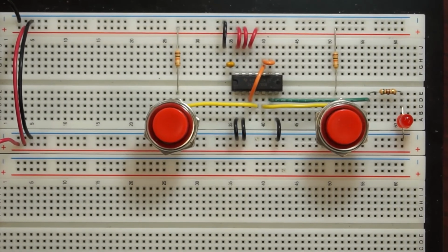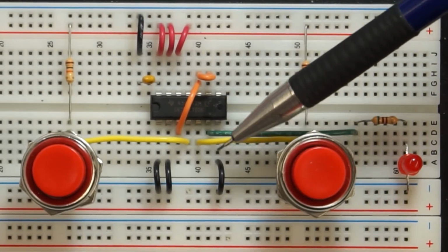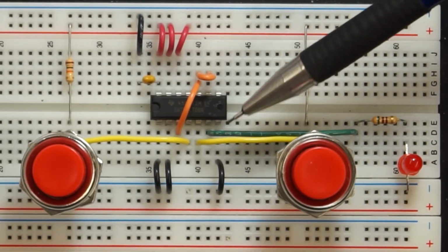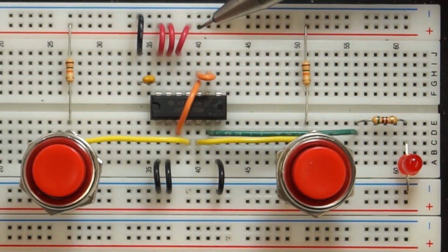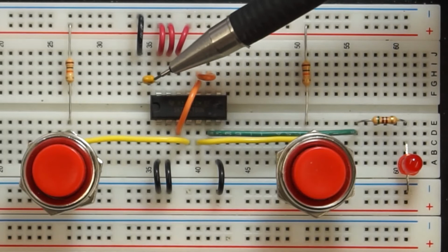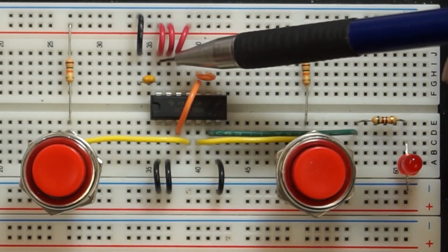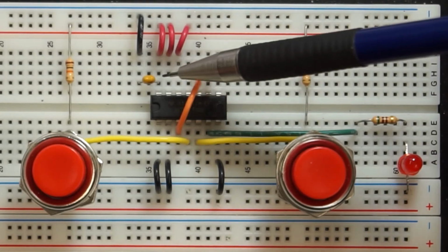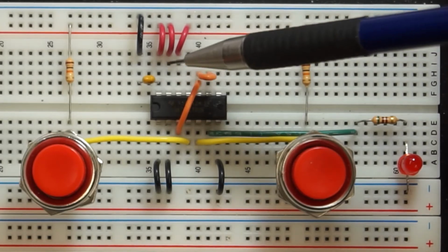And here's the breadboard with the circuit wired up. This is the NAND chip. This black wire connects pin 7 to ground. This red wire connects pin 14 to the positive power supply. This is the 0.1 microfarad capacitor. Note that current which flows into pin 14 has to pass by the top end of this capacitor, giving it a chance to process spikes.